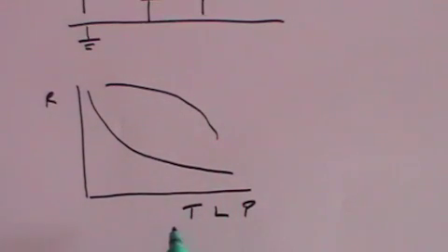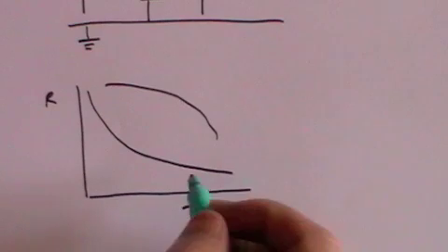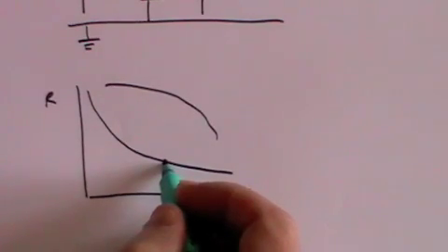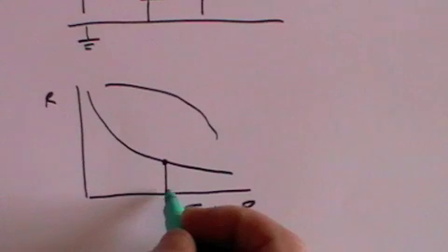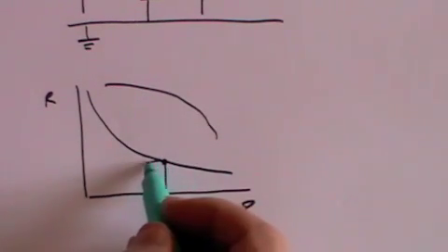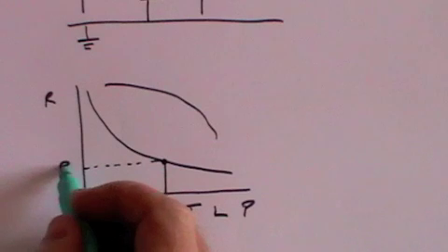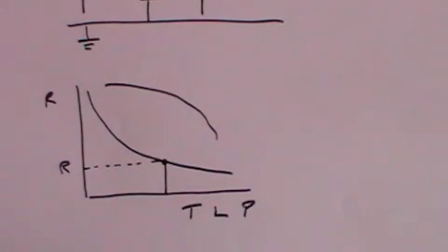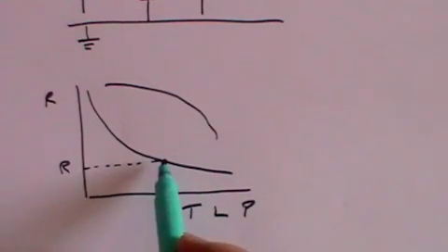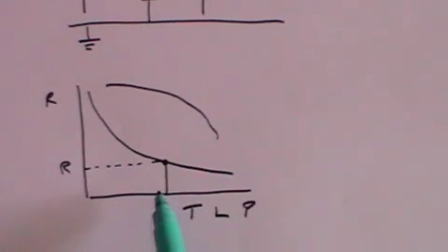And that means that if you want to say that you want the light to come on, let's say, when the lighting level in the room gets to that value, if this is a measure now of the light, then you want that resistance to be the critical resistance which will cause the operational amplifier's output to change from, say, positive voltage to negative voltage. And the only way you can do that is to calibrate the sensing device first. So there's no straight line.